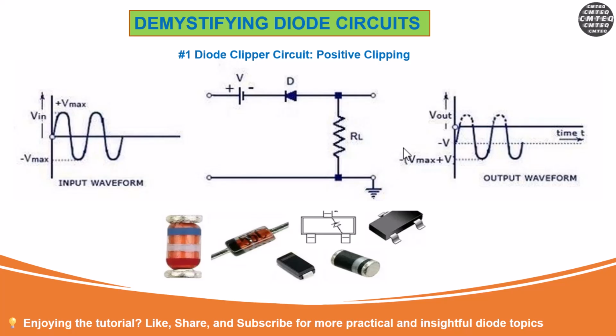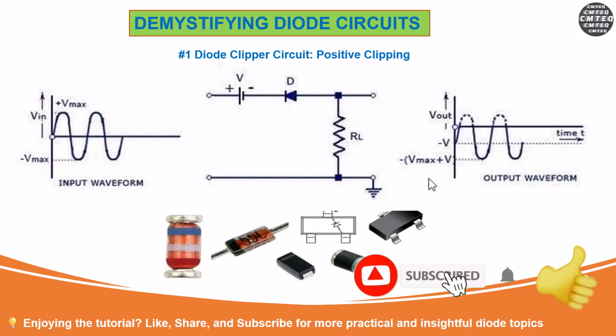In summary, positive diode clippers basically remove voltage above the specified level. The key components are your diode, your resistor, and your voltage source. We basically set the clipping voltage, and these are widely used for signal conditioning and protection circuits.